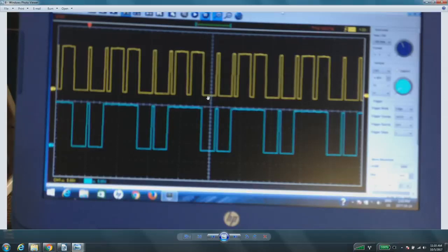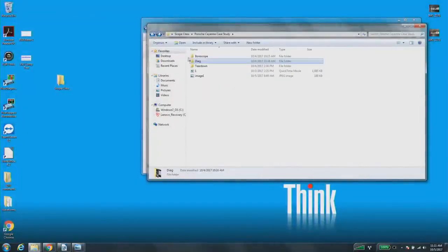So when we have those long trigger points, those long sections of metal passing our sensor, that's when we sit low here. Then we have a short gap, and then we have our long trigger point again, and then a short gap, and then we have a short trigger piece here, goes back to long, back to short. We're missing those two trigger pieces on the crank sprocket or the trigger wheel or whatever you want to call it. So at this point, he's now verified the problem.